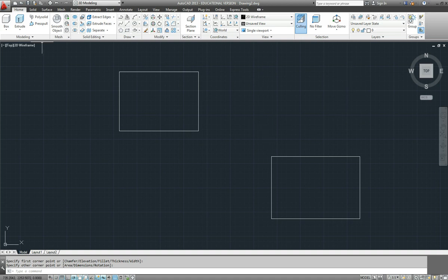Now, there's a couple of ways to do it. Using the techniques that we've learnt previously, we can acquire a point, hover on a point for a few seconds and drag across, and you see we get a tracer line coming with us. We can then hover on a second point, acquire that point, and when we move up, it picks up our previous tracer line, and we click and we have an exact projection of those points. So this is one of the more recent innovations in AutoCAD that we can use to acquire points, sometimes called scrubbing points.